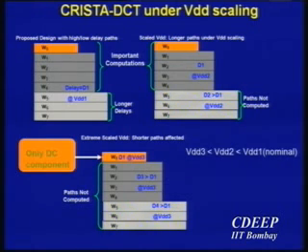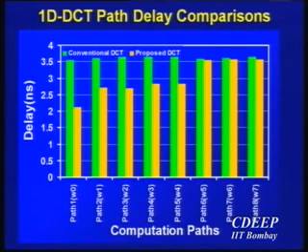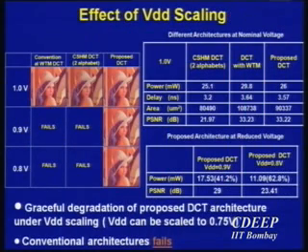So in other words, if I were to design this, I can fool my logic synthesis methodology such that I can give my Synopsys tool a slightly different constraint for W0, W1, W3, W4, and so on. If I don't put any constraints in a conventional DCT, they're mostly going to be computed around the same time. But if you do give some constraints, saying, hey, this is more important, so I need to finish it faster, and this one I can give a little more time, then I'm going to do different kinds of sharing, different kinds of things. And if I do that, this particular one shows the new DCT, new W0, W1 that I'm actually computing. Now, what is the effect on the image? That is kind of interesting.